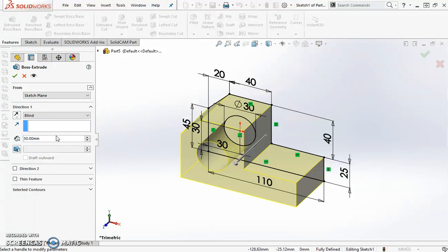Then we also need to look at the Z in its center of mass and see if that's positive or negative. So in the activity it says it is positive, which means it's going to be coming forward in a positive Z. If it was negative, we would have to send it backwards by hitting this reverse button. But we don't need to do that for this activity because it is positive. So we'll hit the green check.